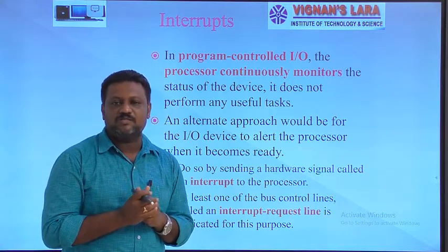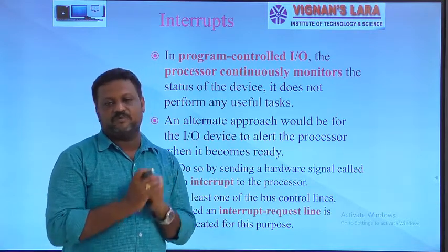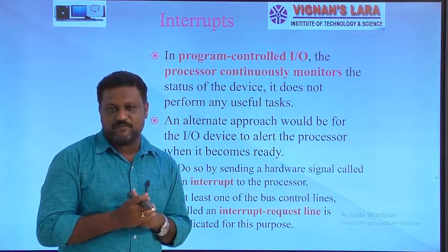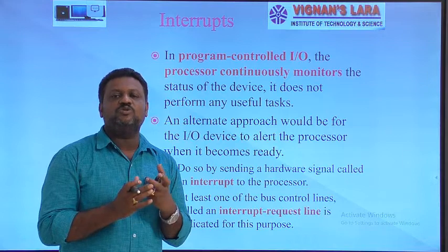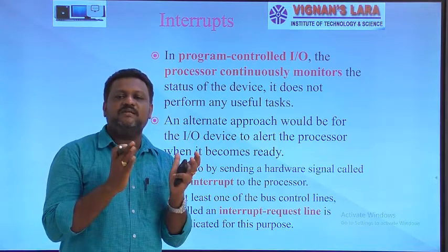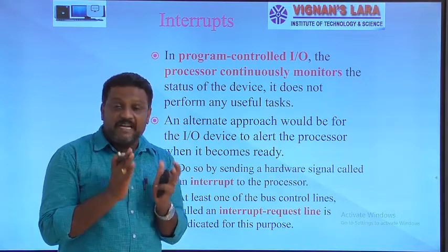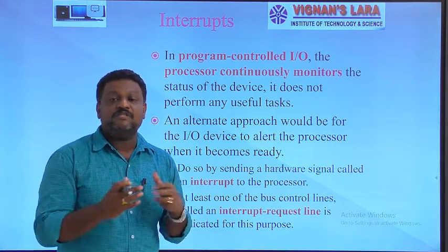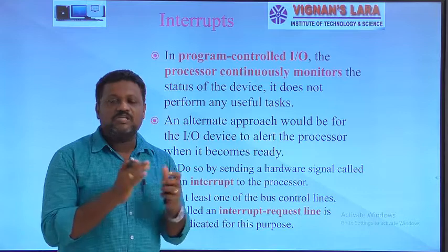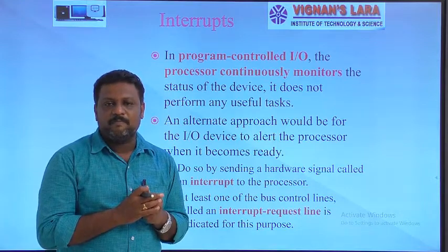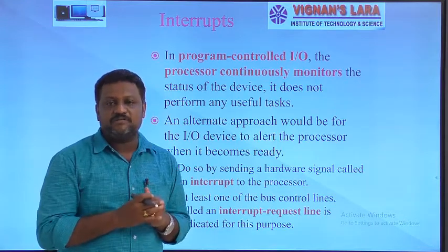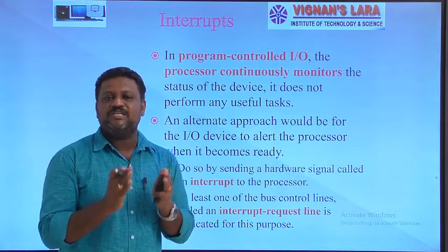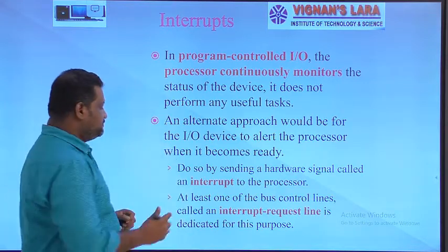In order to overcome that difficulty, we shifted to the second type of I/O data transfer method, interrupt-driven I/O. In this case, the interrupt signal plays a vital role. It means that in order to reduce the idle or waiting time of the CPU, whenever the device is ready to communicate with the CPU, the device informs the CPU by issuing a special signal, which is called an interrupt signal.